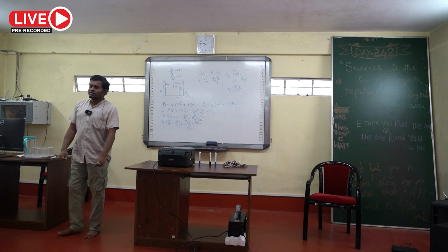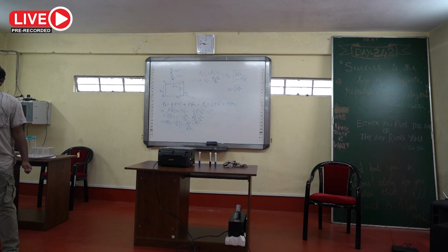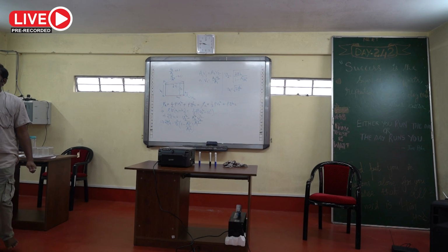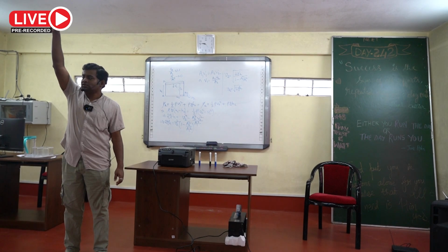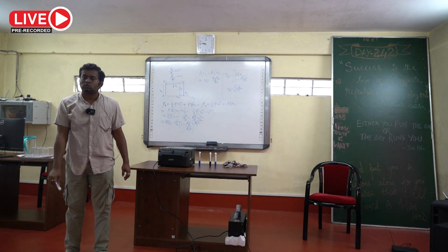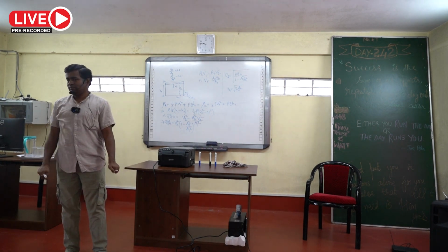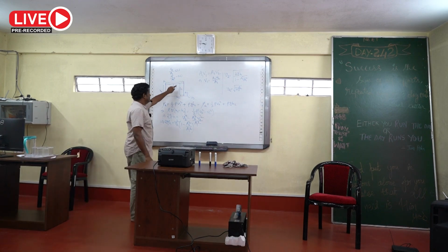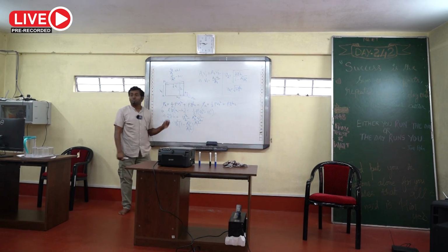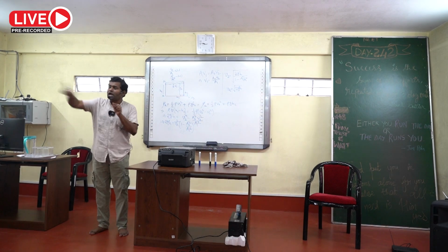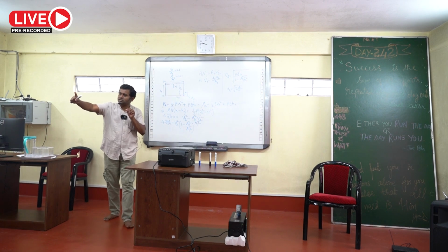You earlier got this result in kinematics, motion under gravity. Suppose an object is taken to a height h and then released. So what will be its velocity of free fall when it is close to the ground? Root 2gh. The same velocity will come as if the water from this point is freely falling and ejecting from this, and this water will come out with a very high velocity. Once this pinhole is opened, water will rush outside.